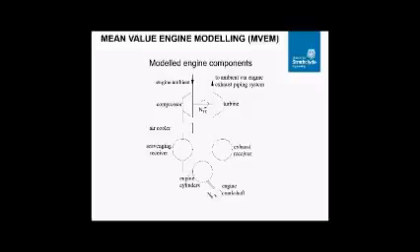The engine exhaust gas is expanded in the turbine, thus producing work, which in turn is utilized by the compressor for compressing the air. In consequence, the pressure and, as a result, the density of the air contained in the engine intake manifold is increased. Thus, the amount of air entering the engine cylinder is greater, allowing more fuel to be burned, and as a consequence, the engine produces more power without increasing the engine size.